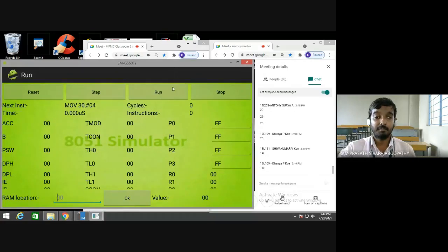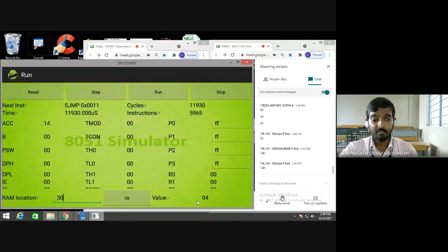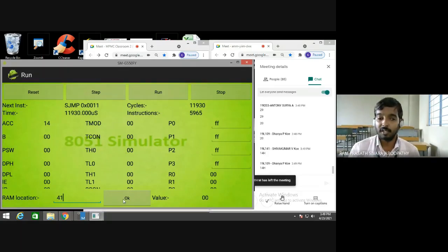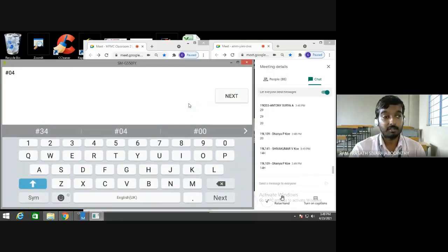I'm going to run the program again. Okay, start. So let's see what is in 30. What is in 30? Okay, the value 4. What is in 31? The value 5. In the RAM location 40, we have 14. So what will we have in 41? 0. Fine. We don't have a result greater than 8-bit. Okay. Suppose here I am going to give both data as FF. Let's see what result comes.